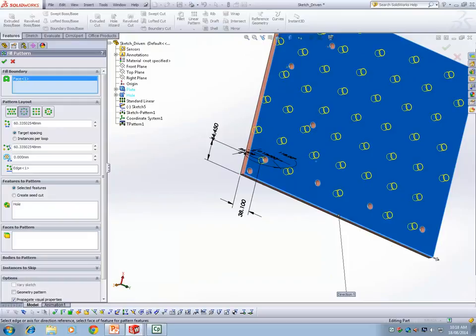When you're using a fill pattern, it uses the entire face and tries to give you a random fill. Then again, you can go into your skip instances and skip some of them. Say for example, if you are drawing a landscape layout, it has got some trees in the garden, quite random, you can draw them by fill. If it is with randomness, we can use a fill pattern.